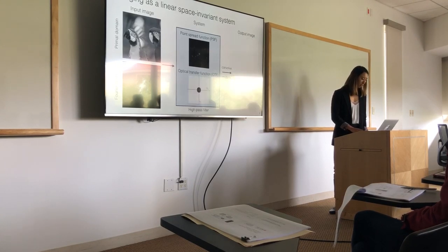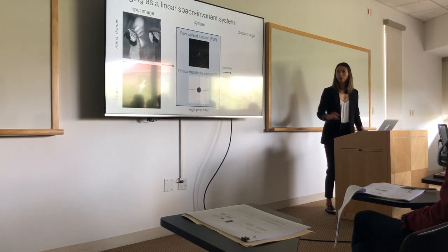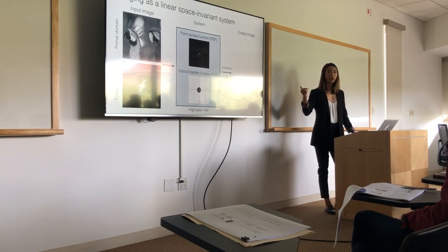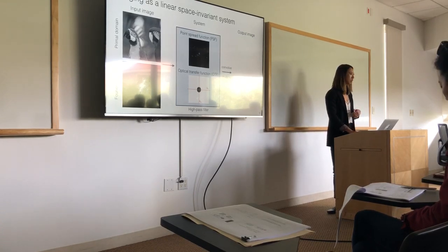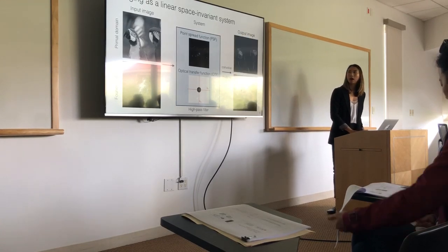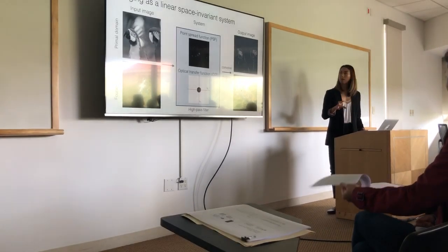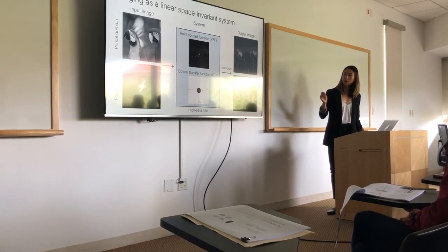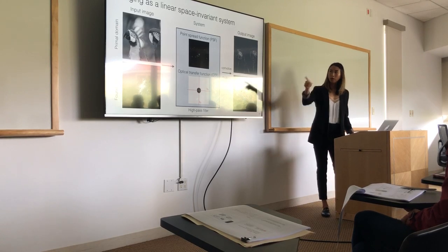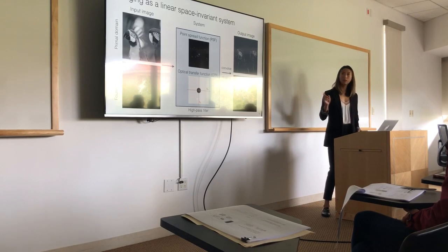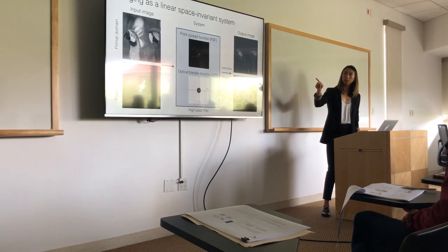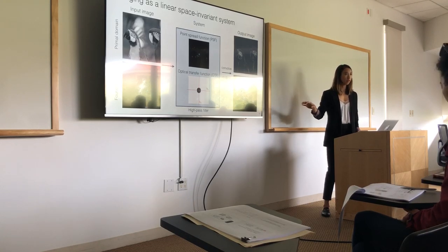As another example, if we have a high-pass filter, we would kind of reverse the colors in that OTF. So now we're allowing the high frequency information to pass through, blocking the lower frequency information, and as you might expect, we now have only the sharp information of that image, which just has the edges of those pairs. And the way we get from the input image to the output image is either a convolution in the primal domain, so convolving the input image with the PSF, or multiplying the Fourier representation with the OTF.